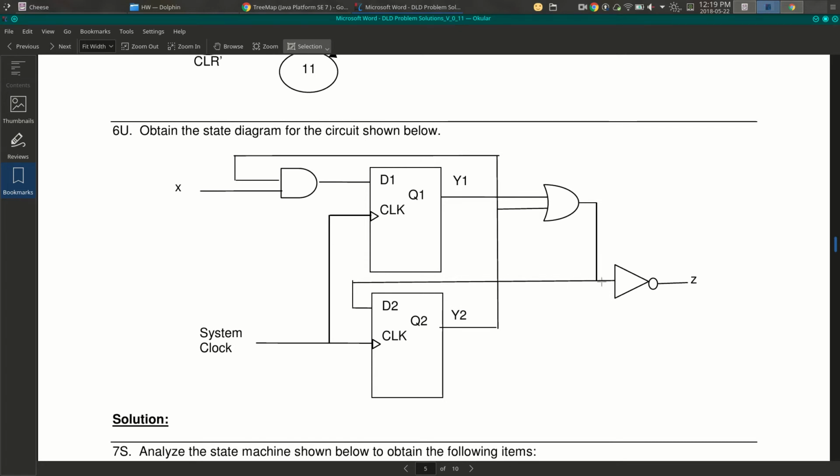And if we follow this particular path, we find the output of this OR gate. Someone back there said it. So this is generating an output here. It's feeding the input of the inverter, and it's also feeding D2. So D2 would be equal to the OR of, well, this comes from Y1. And the second input, well, it can't come from here because that's an input. Let's trace it down. Oh, there it is, Y2. So the output of this OR gate is Y1 or Y2, so that's what D2 is equal to. Does that make sense?